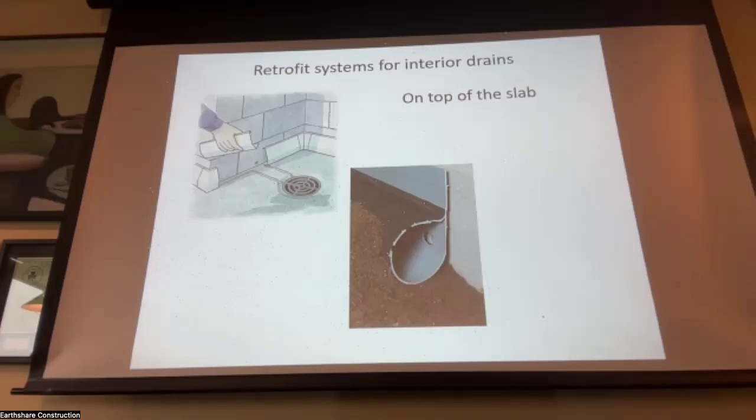Exactly. So in these scenarios where they're working on the inside of the foundation, like with insulating and waterproofing, is that because it's easier than excavating the outside and doing the outside, or is it actually better? It's usually less expensive, and mom doesn't want her roses dug up. Right, okay. But if you could do it on the outside, it would be better. You always want to prevent it from coming in the first place instead of having to remediate it. Yes, good question, and that applies to the insulation as well as the waterproofing.